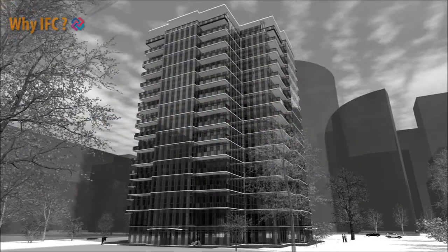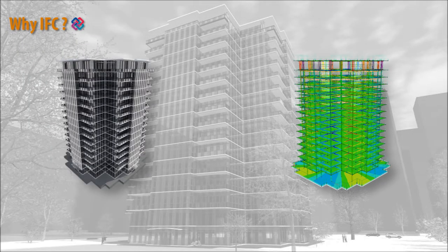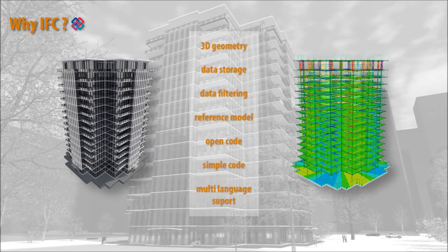and AxisVM. Let's summarize the main features of the IFC data exchange file format, which is the basis of our OpenBIM workflow solution. IFC describes the precise geometry of a 3D building element. For example, in case of a column, its height, width, and cross-section. In addition to geometry, additional building element properties can be stored. For example, its material or fire rating, acoustic rating, and the function of the element.